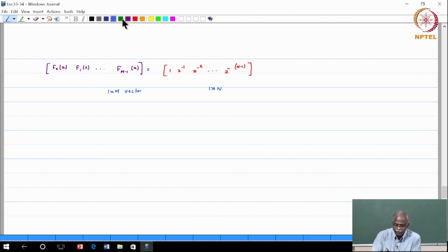Okay. The next part of this are the polyphase components. All the polyphase components of f0 must be along the first column, because only then they will get combined by the delay chain. So, this will be g00 of z power n, g10 of z power n, dot dot dot, g n minus 1 comma 0 of z power n.